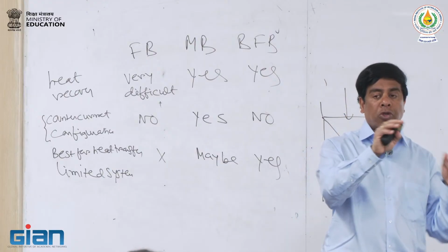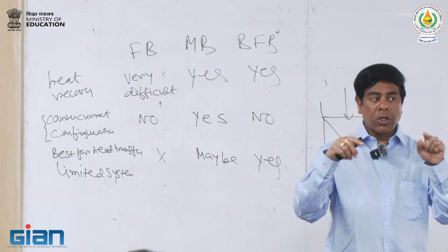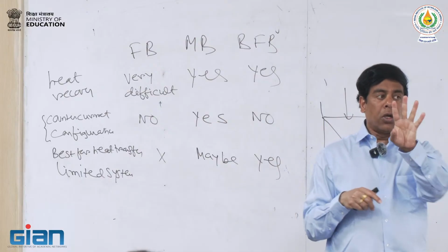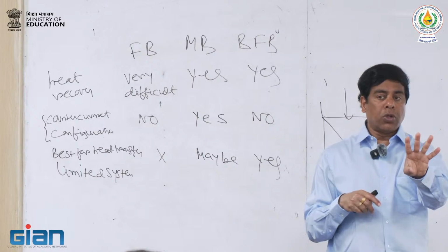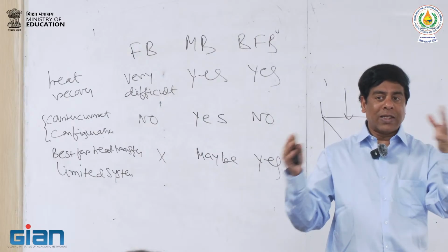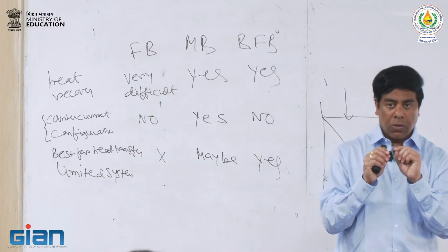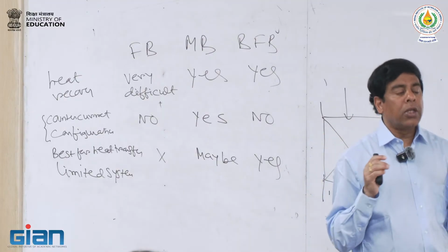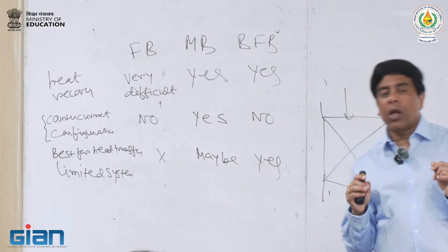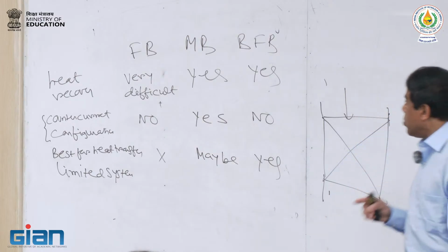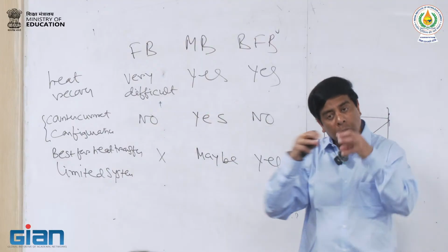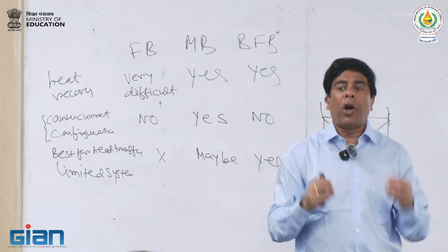And whether the fixed bed versus the moving bed helps: a moving bed definitely has a higher mass transfer coefficient. But remember Professor Sridhar's lecture: when you consider the mass transfer coefficient, there are two mass transfer coefficients we are talking about, right? One is external, that is interparticle, and the other is intraparticle.